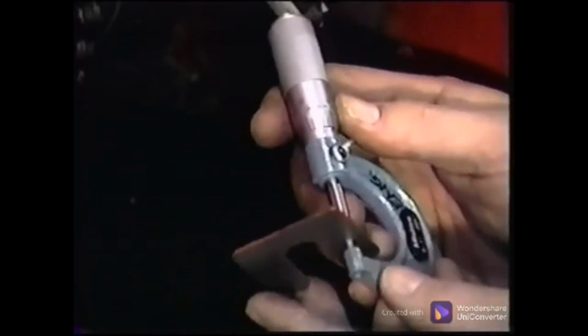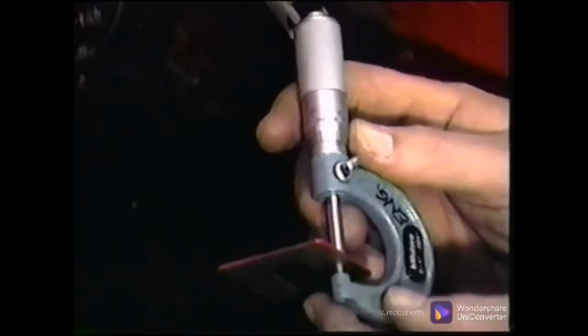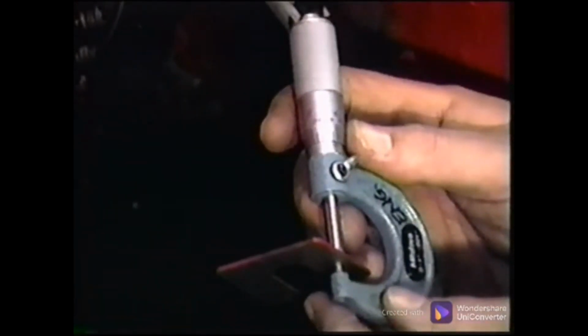Check the condition of any existing shims, cleaning them and inspecting for burrs or rough surfaces. Discard any distorted, rusty, or aluminum shims. Verify the thickness of shims over 25 mils thick with a good outside micrometer that has a resolution of at least 1 mil. The shim should be the same thickness throughout. Mark the thickness on the good ones and record the thickness that was under each foot.